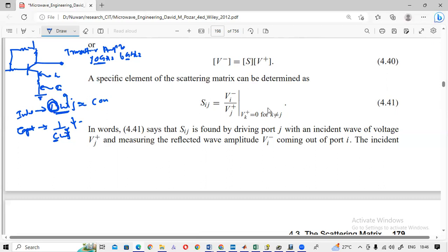So if you want to short this circuit, sometimes due to this inductive effect it is not a perfect short, because there is some impedance there because of omega. This L may be very low, but omega is very high.